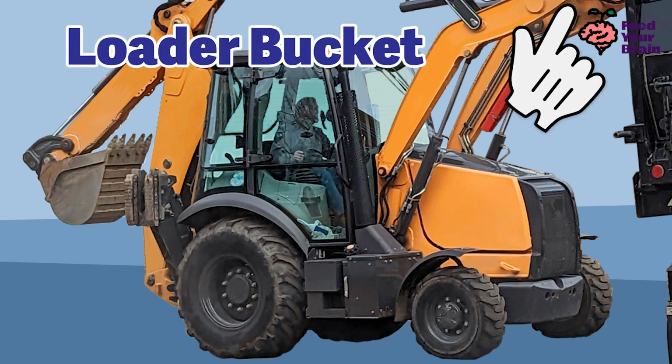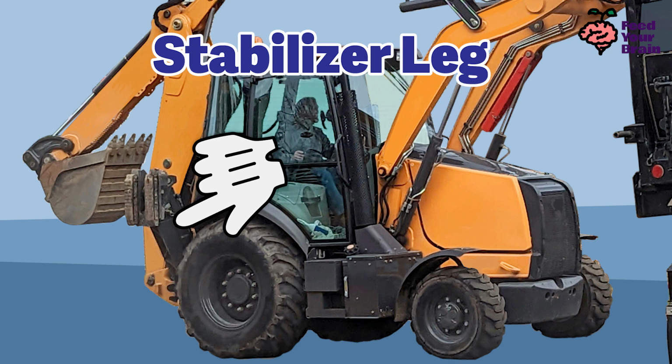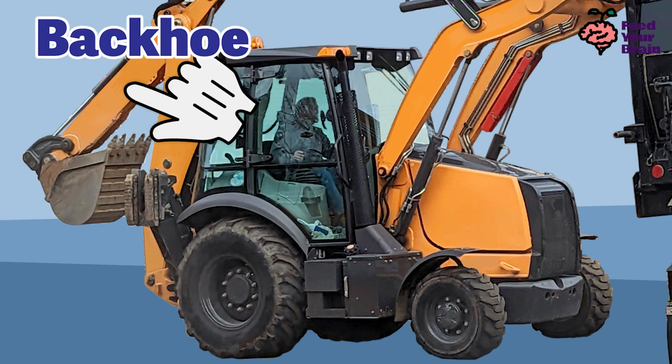Notice when the loader bucket is being used, like it is here in this image, that the stabilizer legs are up and therefore not being used. You only lower down and engage the stabilizer legs when the backhoe is being operated.